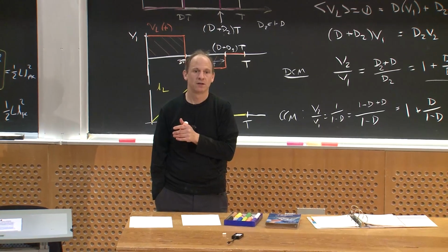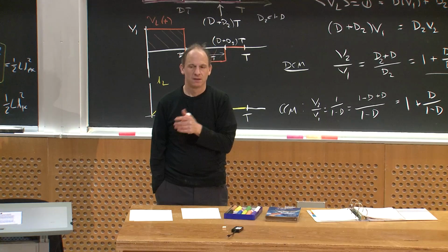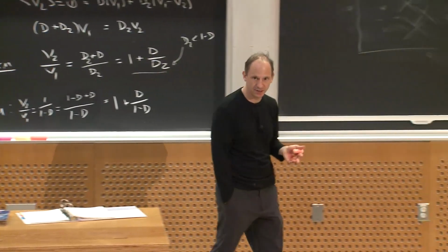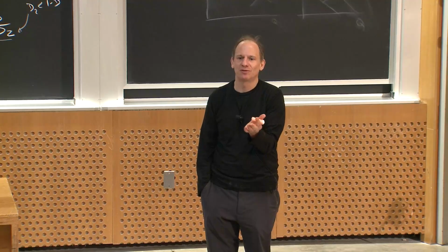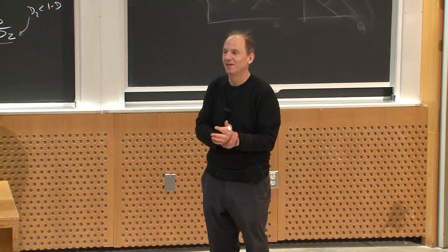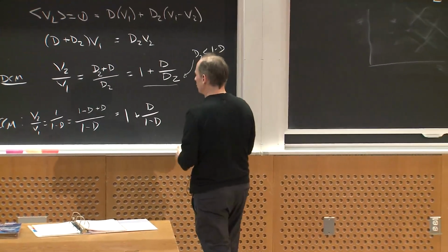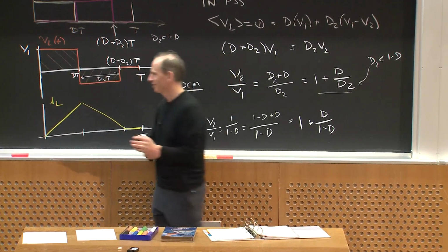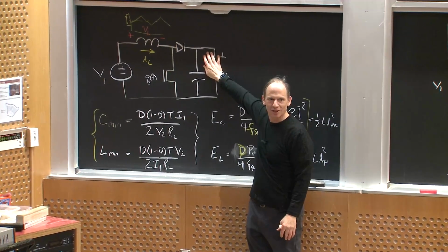Yeah, Lawrence? How do we know that we stay in periodic steady state when we go through these different modes of operation? That's a good question. It's a question of, will it reach periodic steady state? You can do this analysis and find out. It generally will settle, because you can solve for these things; the boost converter will end up in periodic steady state unless, suppose I disconnected this load resistor. That's equivalent to making R equal to infinity, right?